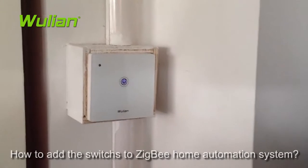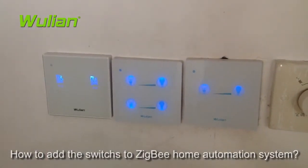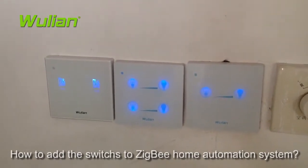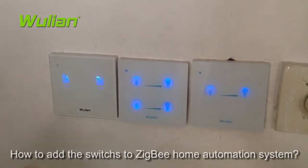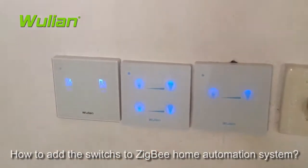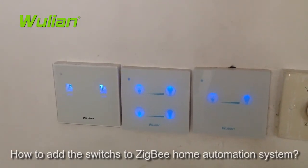It's very easy. For our wireless touch dimmer switch, it is also the same way. After taking off your old switches, you just need to click 4 times of the function key. Then add this wireless touch dimmer switch to our Zigbee networking.